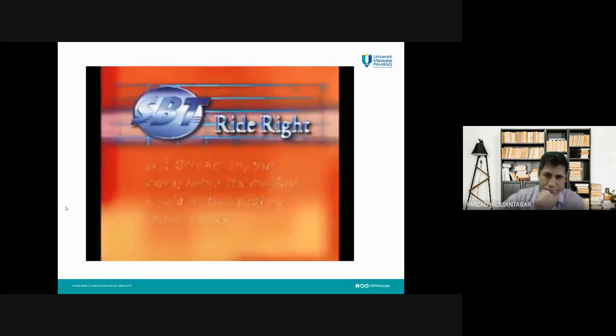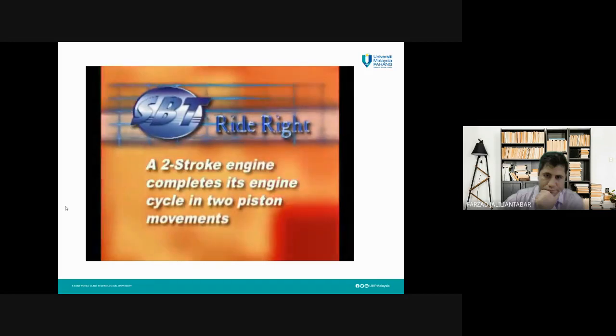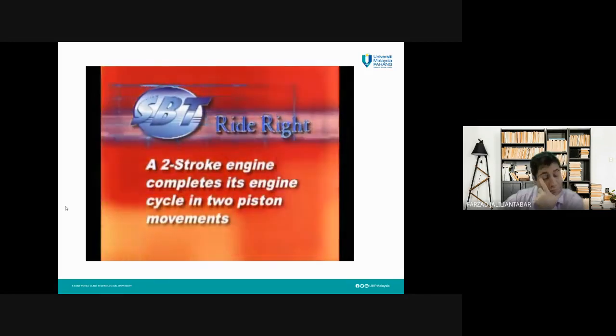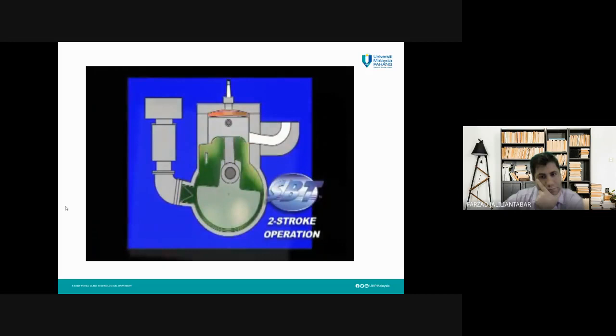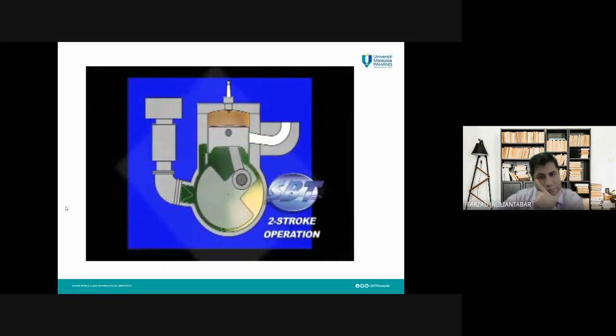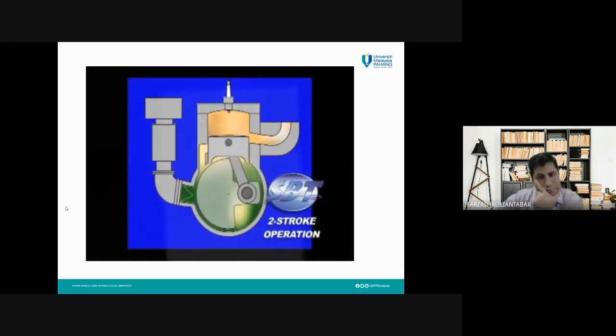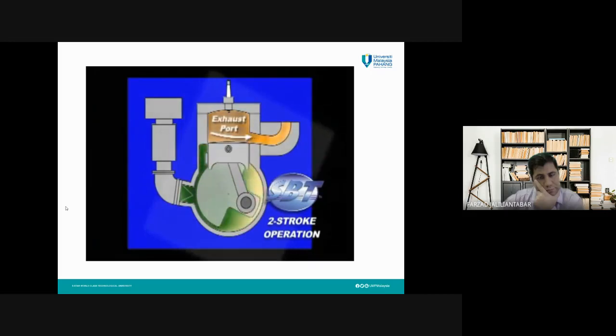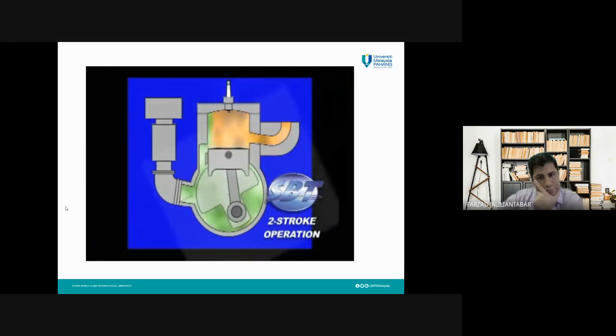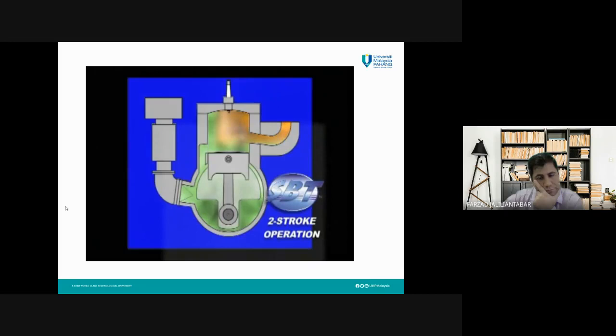forward. A two-stroke engine is designed to accomplish its complete cycle in just 2 strokes. During its power stroke, the ignited air-fuel charge forces the piston down until it reaches an opening on the side of the cylinder called the exhaust port. As the piston continues down, it pressurizes the air and fuel mixture under the piston that was drawn into the crankcase during the previous compression stroke.